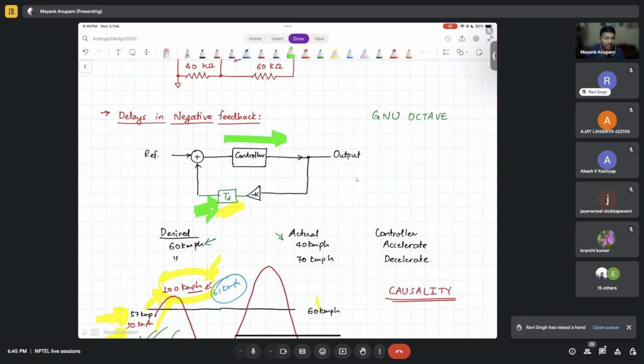I mean, this actually might sound very counterintuitive, but that's how it is. When you go further, you will see that when there is a delay in the system, you will have to reduce the unity gain bandwidth of the loop. That will come later. Unity gain bandwidth actually translates to the speed of the loop. Okay, that's the meaning of unity gain bandwidth in a loop.